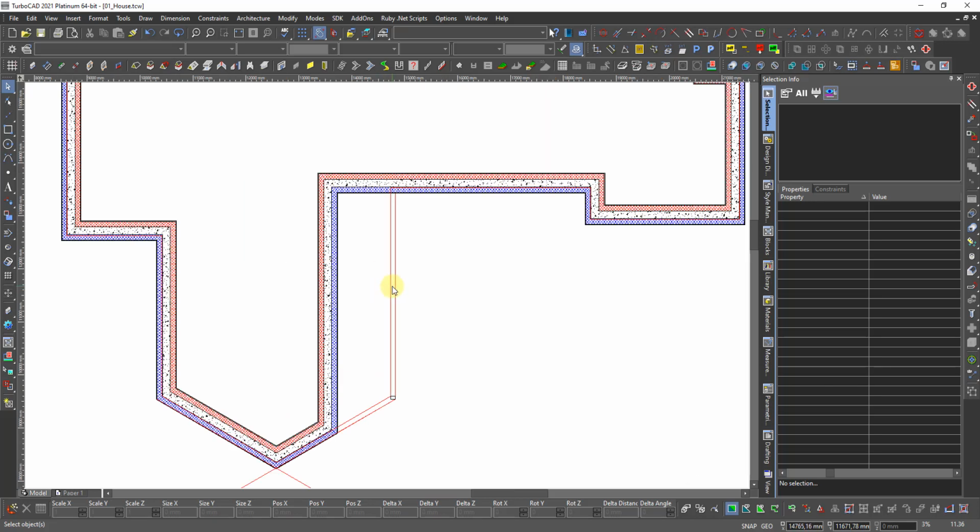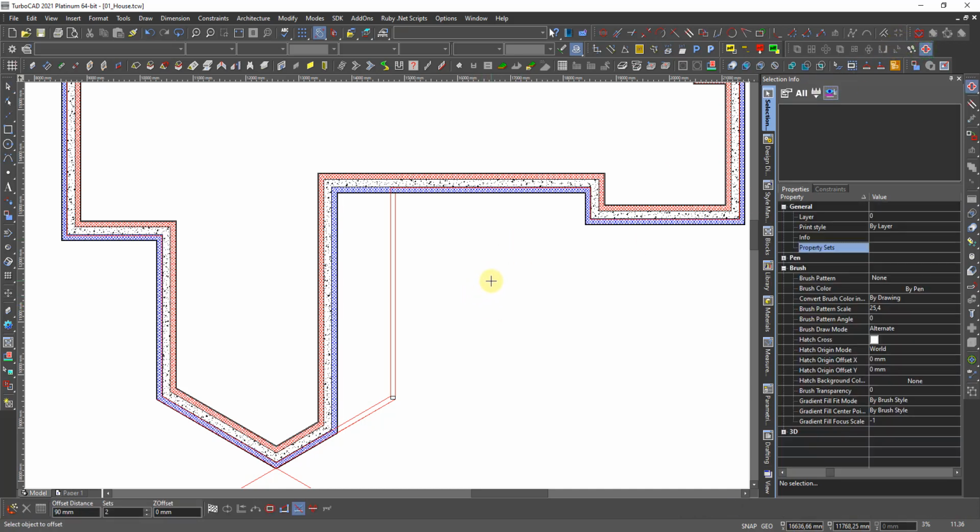I should have this cover the inside of the wall, and that was 215 from this one. The total wall thickness was 215. So then I offset 215, that polyline, as you want inside.